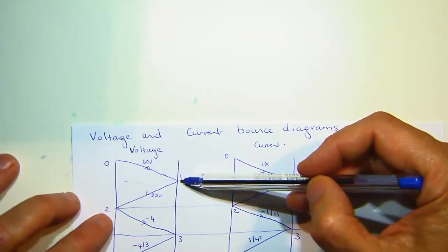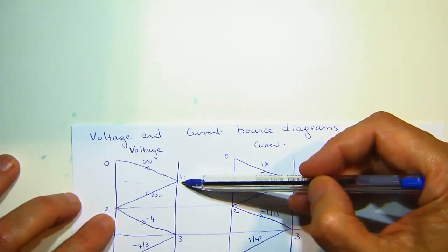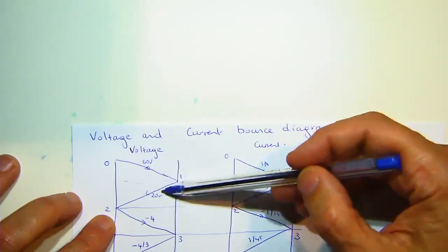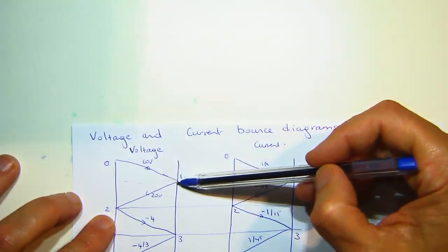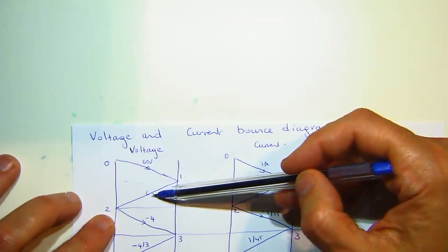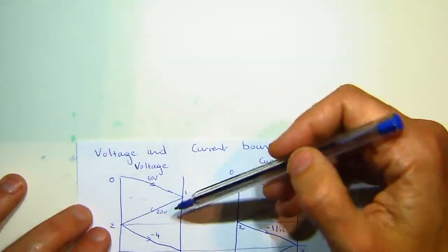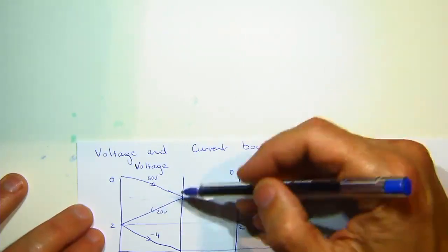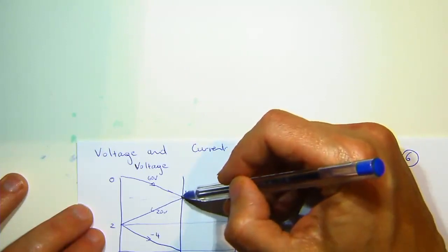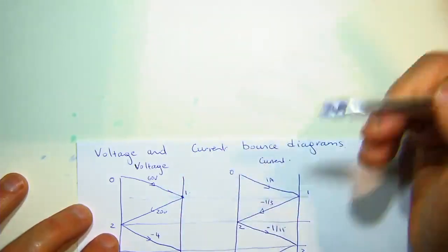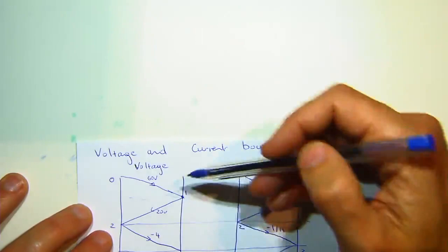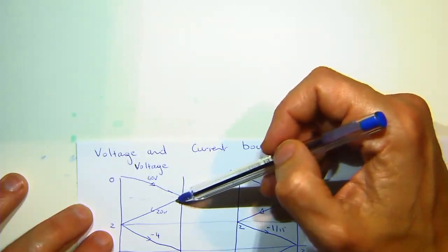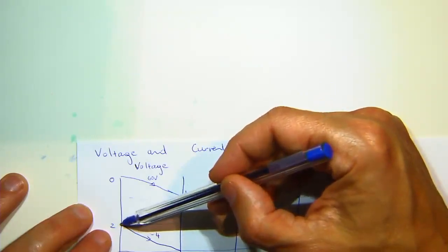Now, what have we said? Well, we've said that the reflection coefficient for the transmission line load is 1/3. So if the initial voltage is 60 volts, the reflected voltage is going to be 20 volts. Now let's continue this. The voltage wave has hit the load, and it is reflected. Now, can anyone tell me what they think the voltage at this point is going to be? 80. You're right, because they're both positive. Good. So now the signal is reflected, and it travels and hits the source.